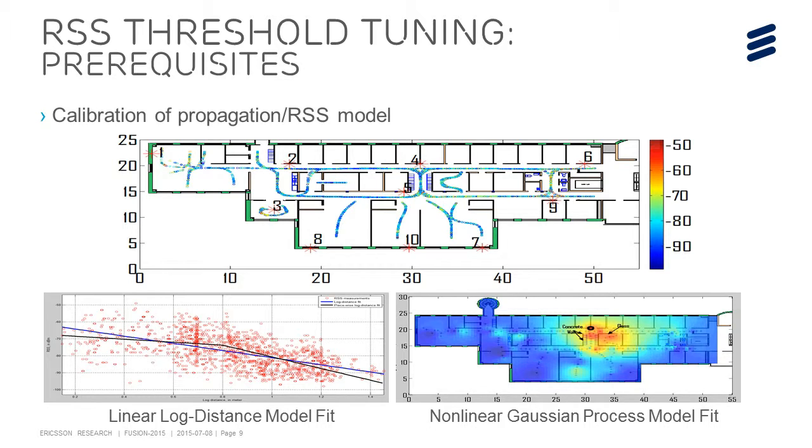A moderate scale measurement campaign was conducted during normal work hours. Throughout the measurement campaign, the mobile device equipped with BLE chipsets receives data packages from the BLE beacons and measures the RSS. Around 12,000 RSS measurements were collected along 52 predefined tracks. For clarity, we depict the 52 tracks all together in the top figure and use different colors to indicate the quality of the observed RSS.